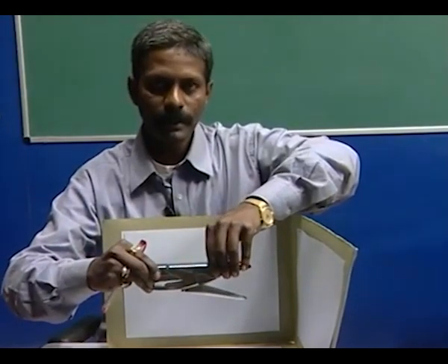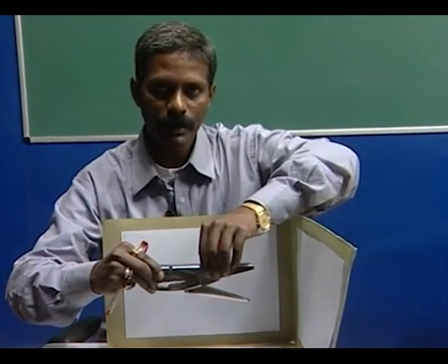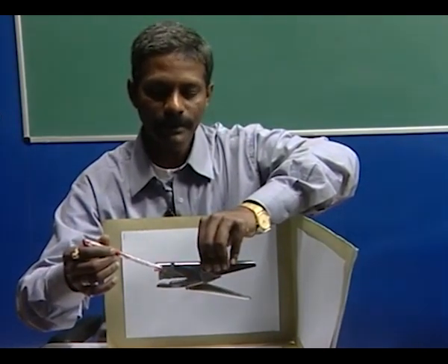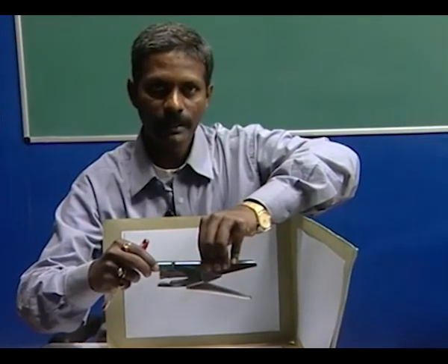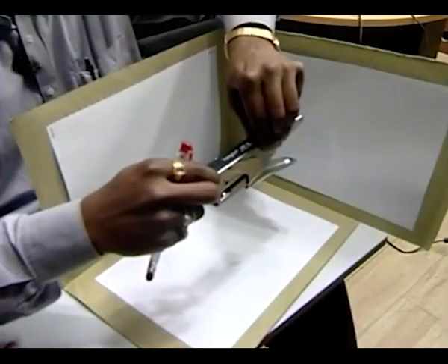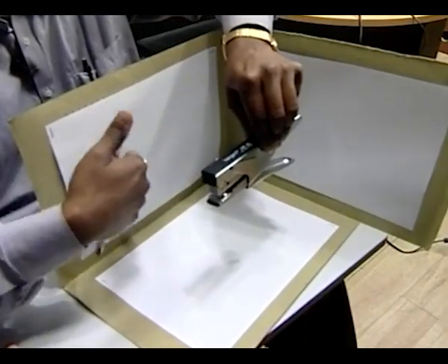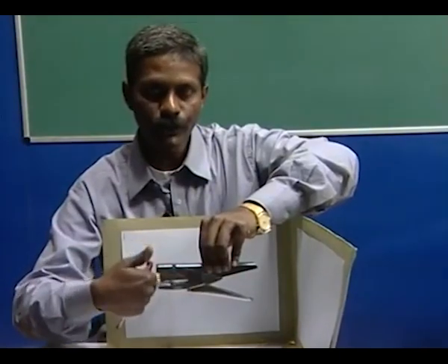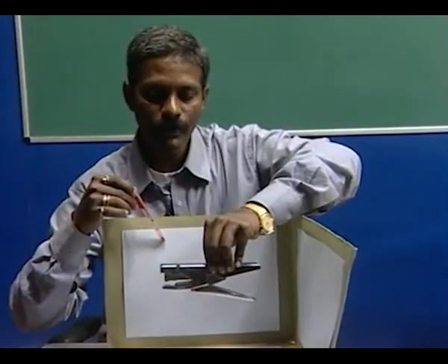Imagine that parallel projections are emanating from you. They are hitting the object, and imagine that the object is transparent and it is allowing all the projections to pass through itself and hit on this plane. So for you, this plane will capture the front view of this object.